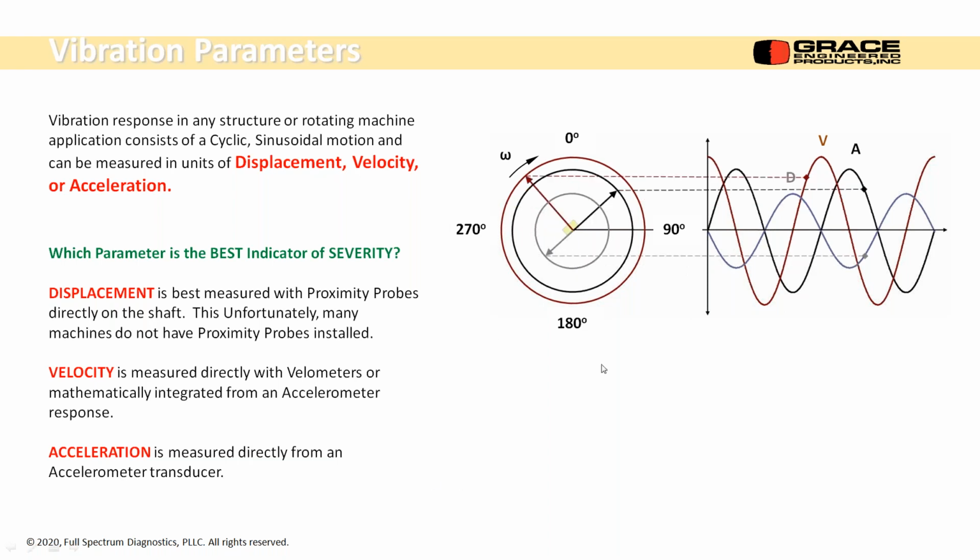We use velocity pretty much. For all vibration measurements on rotating equipment, you can measure it directly with a velometer or something called a seismic velocity transducer. But that isn't the easiest method. The velometers are expensive. The seismic transducers are mechanical, so they can fail.